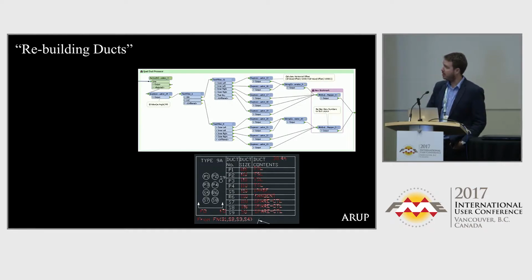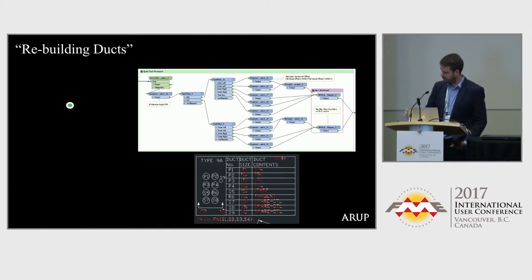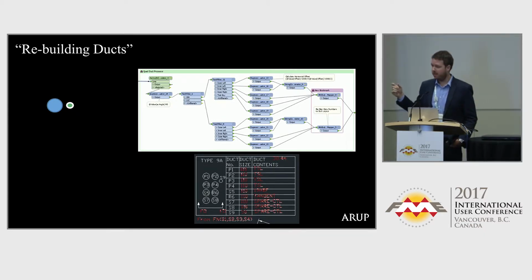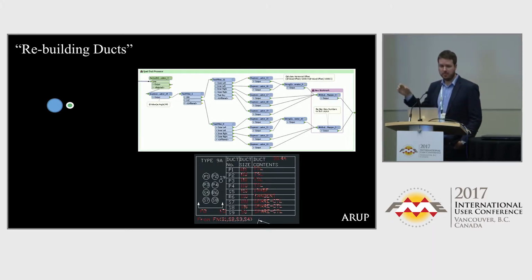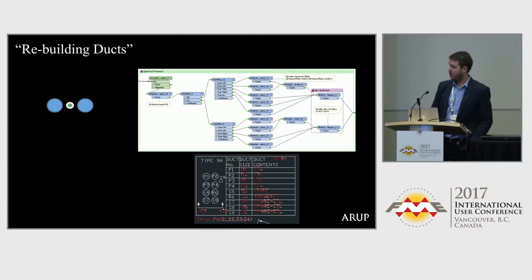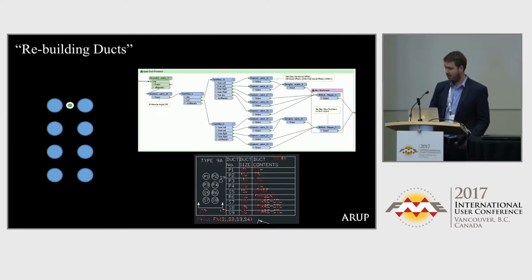Which brings me on to my next slide, which is interactive. We had the center line string, and then we cloned that by the amount of times from the attribute name. Then we would offset. The offsetting we did between each of the ducts was the maximum duct size for the bank. In this case, there's one right down the bottom, which is a 50 mil, and all the rest are 110. So our offset spacings would be 110 mils. I don't know what that is in imperial, sorry. Then we'd offset one side, offset the other side, and work our way down. So these are just vertical offsets and a few expression evaluators.